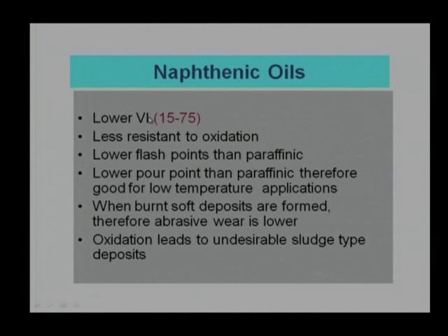Coming to the naphthenic oils, we say they have a relatively low VI, viscosity index. If I am very sure about the operating temperature, if I know the operating temperature is not going to change significantly, then I can choose naphthenic oils, particularly for low temperature applications.